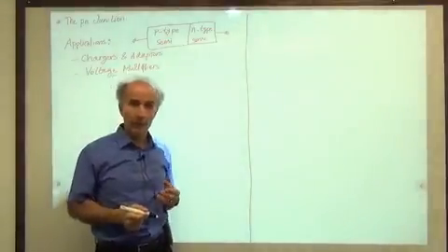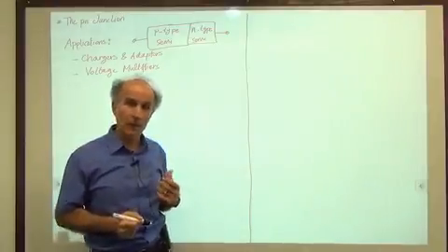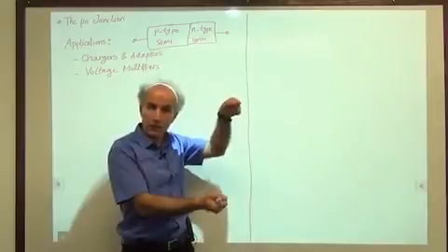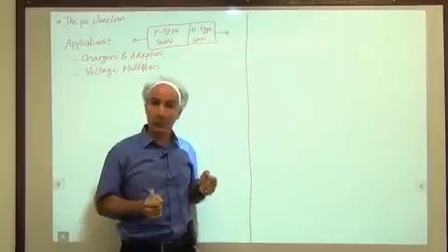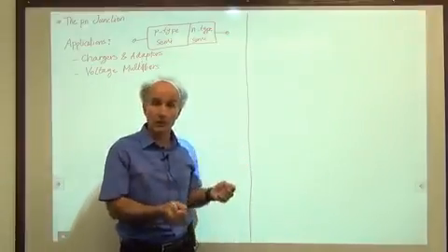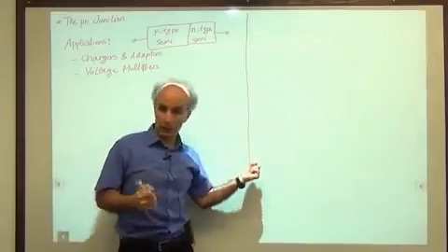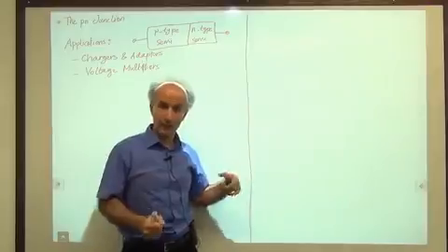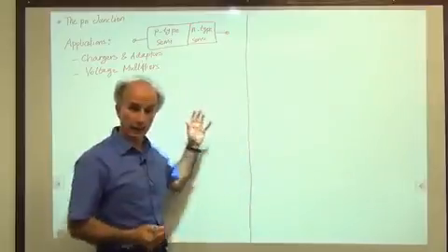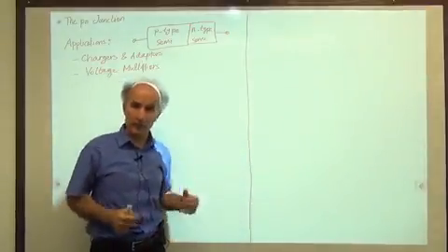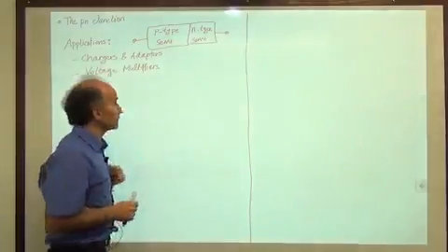For example, there are some devices called photomultipliers used in medicine and other applications where we need a supply voltage of 1,200 volts. Okay? 1,200 volts is a very high voltage. So how do we create such a voltage? The line voltage that we have is 110 volts or 220 volts. So somehow this voltage has to be multiplied up to 1,200 volts. And there, again, we use diodes and capacitors to do something like that. So they have many interesting applications in real life.